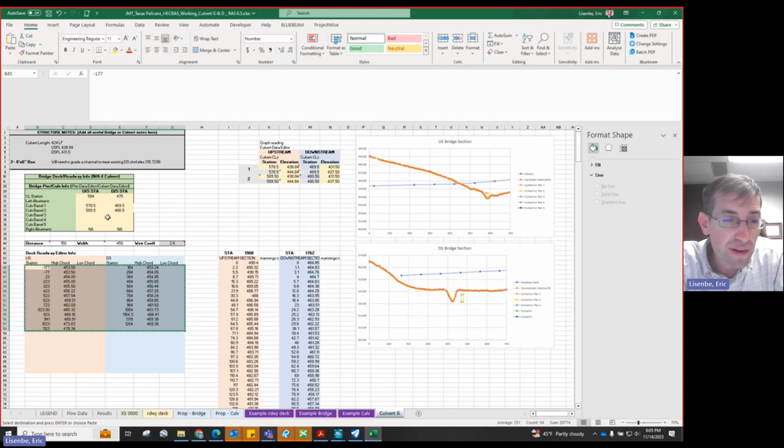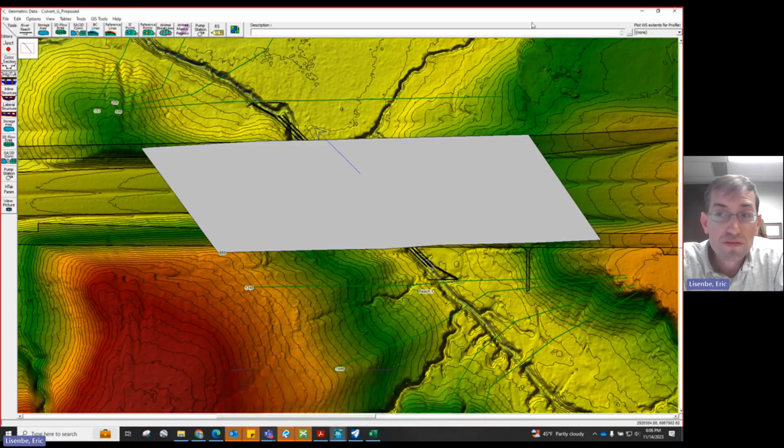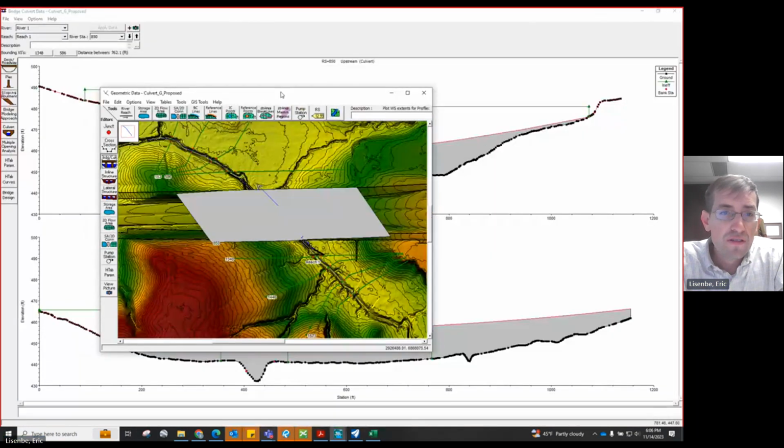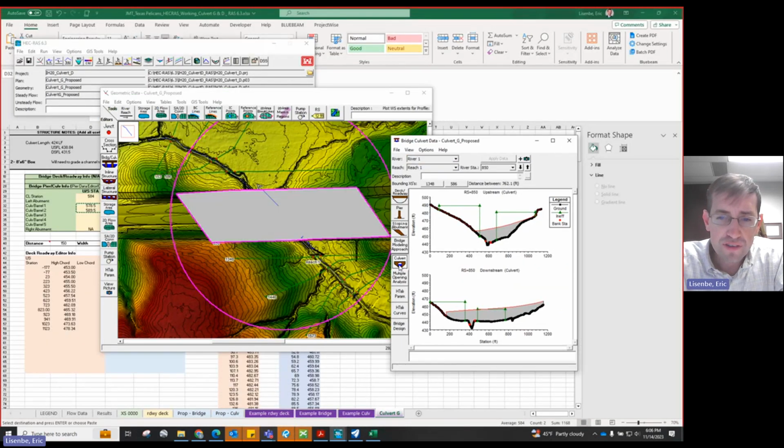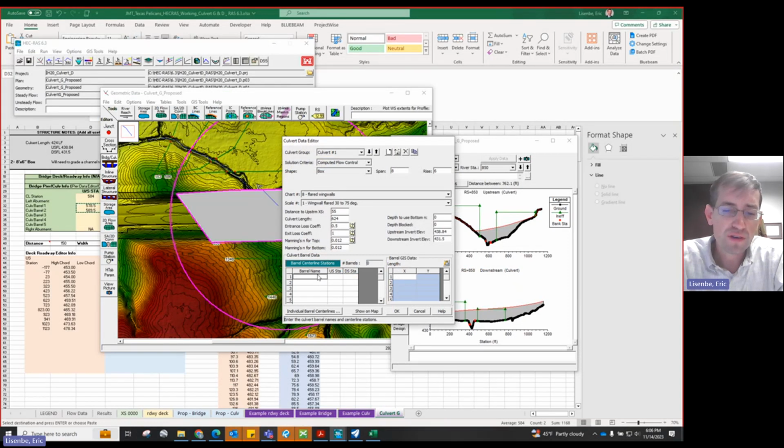And then I can look at my center lines that I've calculated and feed that stuff in as well. So I've got 578. I might even be able to copy. Let's see. On the culvert, we've got barrel 1, and I've already entered that it's two 8x6s. I've entered the flow lines. Barrel 2.